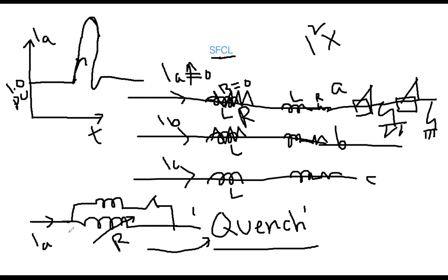So in case there is any fault, this will work as a superconductor. And then again, the circuit breaker will open, and this one will be under quench mode. By then this will be fine. So in that way, at least this one or this one operates, always. There are two in parallel in real practice, these fault current limiters. Everybody, could you follow me? Yes, sir. Okay. Now you understood that basic principle of SFCL.